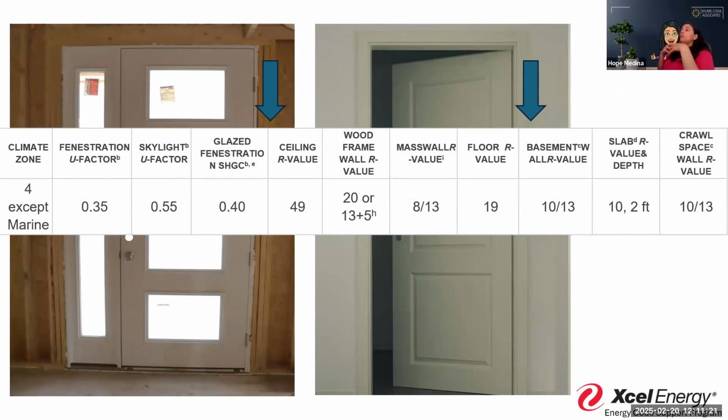They are looking at it as an assembly, which would be that U factor concept. So instead of the U factor of a wall, where you're talking about your exterior sheathing, your insulation between the cavities, the stud values, and then the gypboard, and you add everything up to get your U factor.